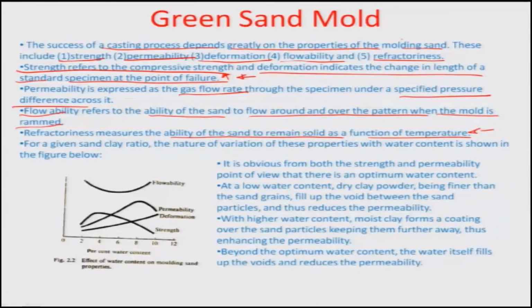The most important part that I would like to illustrate is that this factor, permeability, and in fact all the other factors, strength, deformation, flowability, are dependent on the percentage water content that the green sand mold would have. Let us look at how the permeability would vary.